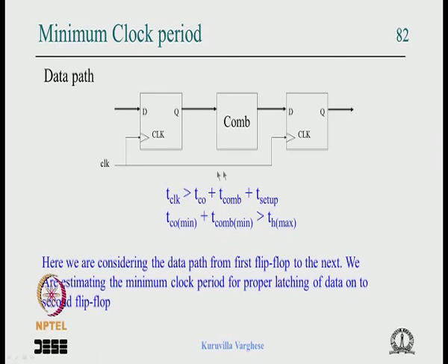In a picture it may not be obvious because you are drawing a block diagram and it looks near, but in a huge chip area maybe the source register is in one corner and the destination register is in another corner, and the clock has to travel through various paths to reach there and can suffer delay all along.